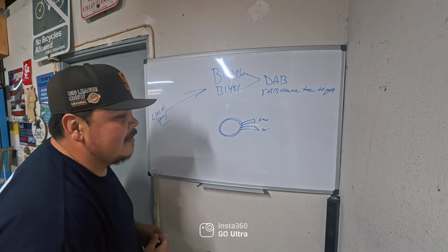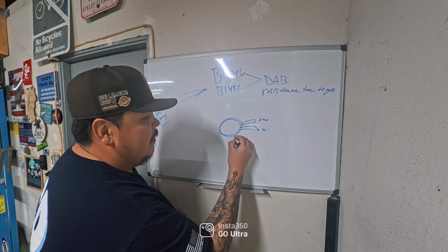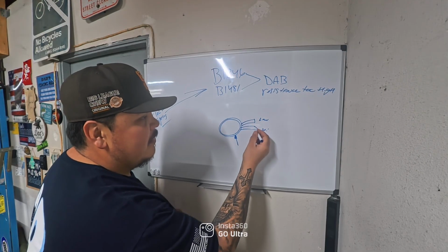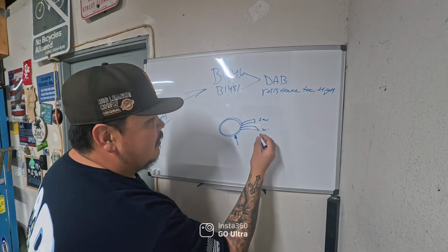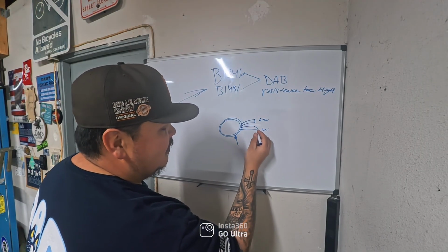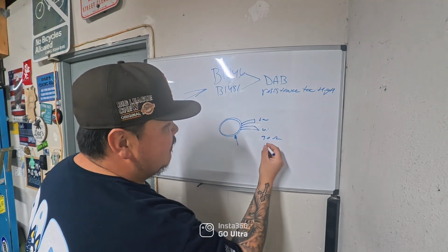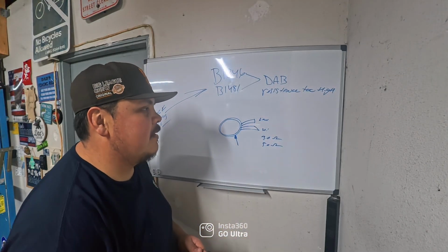So the way that I test it is, you're gonna check the actual resistance on these 2 connectors and see if it's within spec. I don't remember the spec by heart. So if your spec across these 2 wires is 3 ohms and you measured 5 ohms, then your clock spring is faulty.